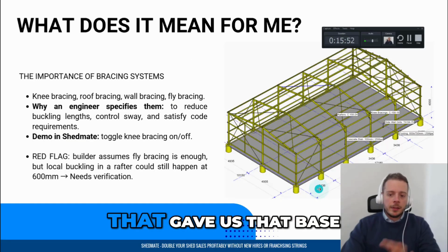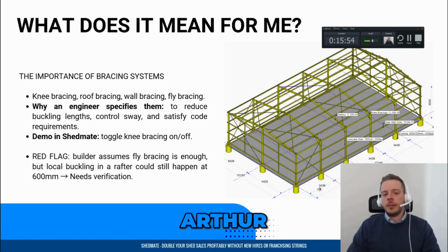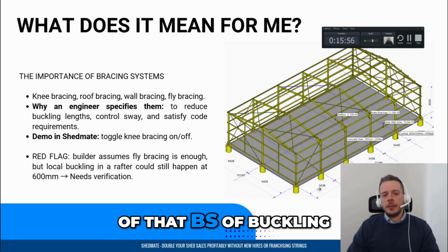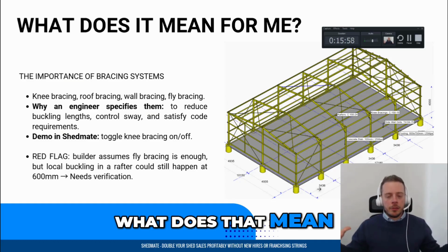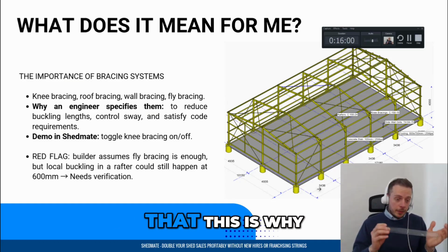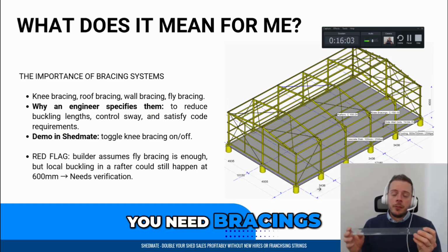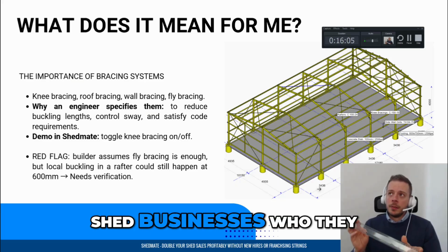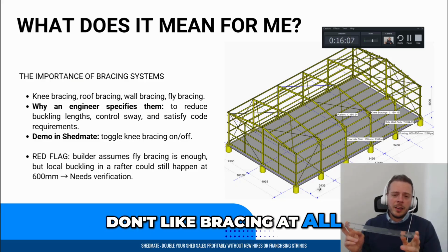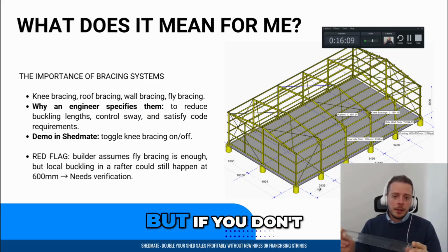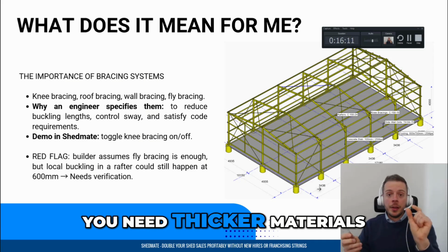Let's move forward because that gave us that base. So, okay, Arthur, you're talking about all of that buckling. What does that mean for me? It means that this is why you need bracing. I've talked to some shed businesses who don't like bracing at all. I know it can be a pain to erect, but if you don't have bracing, you need thicker materials.